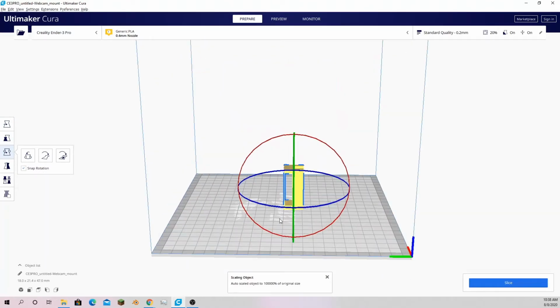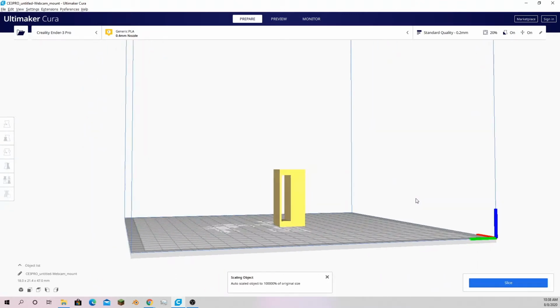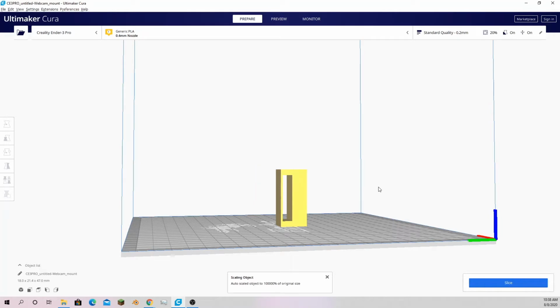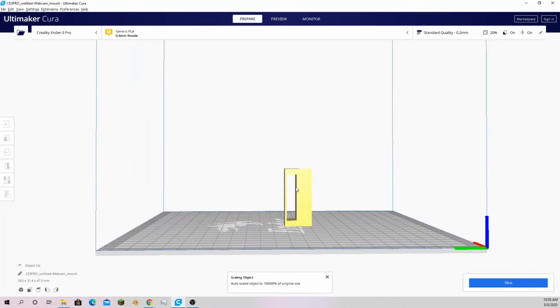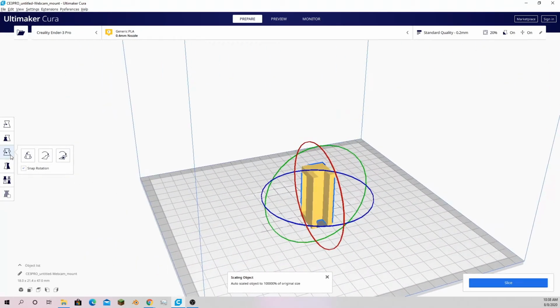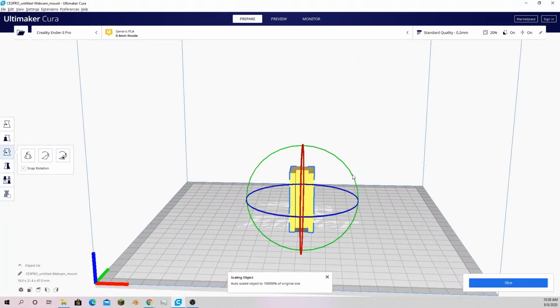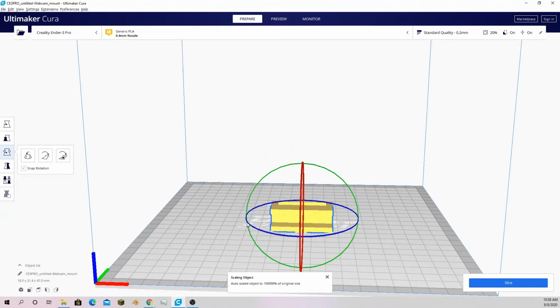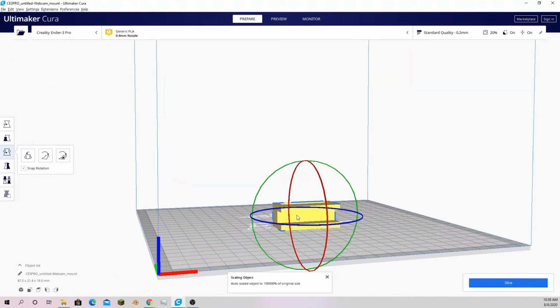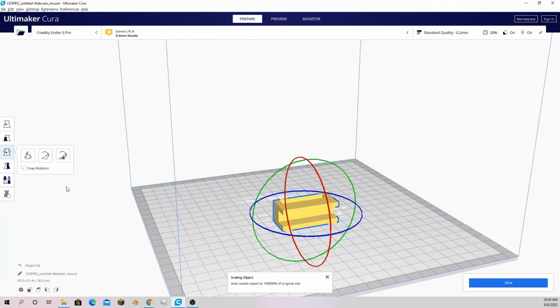because what can happen is when you're modeling something and you're 3D printing it, this could be hot filament, so the filament's going to be soft, so it might sag in areas where there's a lot of plastic hanging, so it has to build supports. So you want to rotate it and have it print in an orientation that doesn't need that much support, so that way you can print faster. So for me, it's better to print like this, where it's just a little bit of support right here instead of a lot of support inside, and so that way it'll print faster.